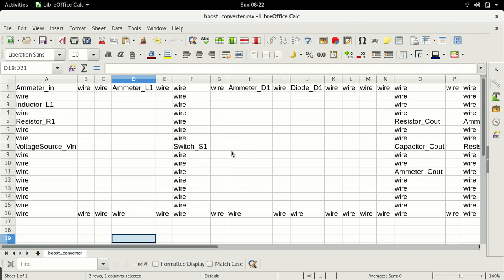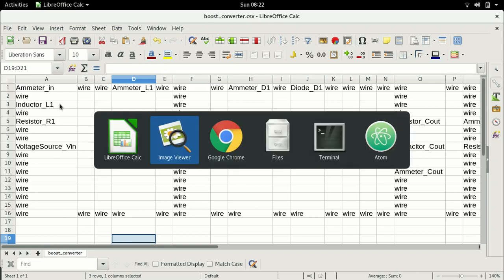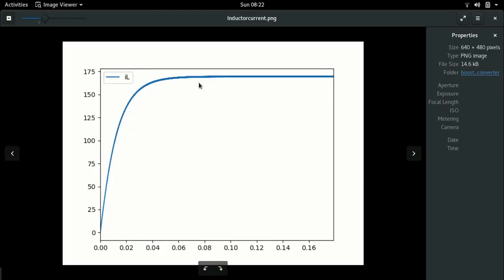That's how it works, right? But when the switch is turned on, the inductor is the only element which is opposing the increase in current, right? The resistor is negligible. And important to note, we've chosen a 1 millihenry inductor, but even that is a bit too large. For a 12 volt system, you might choose only a 200 to 300 microhenry inductor, which means that we would expect this current to be even larger, right?